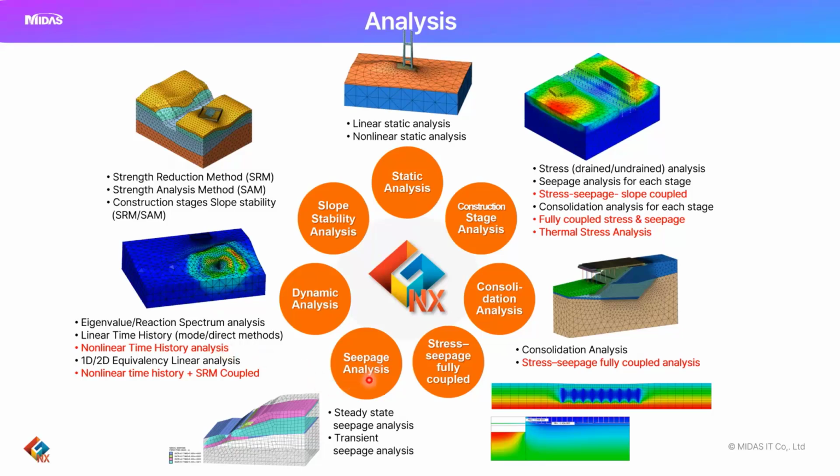We can run a seepage analysis. Suppose you're dealing with excavation wherein you're dealing with dewatering, so it might be very helpful. Both steady state and transient can be run. And this seepage can be coupled with the stress to run a stress-seepage coupled analysis. And you can do a consolidation analysis if you're interested in time-dependent variation of the soil deformation when you're dealing with clay soils and so on.